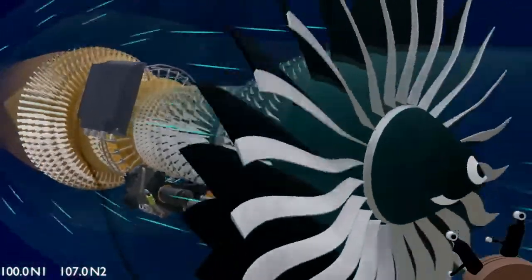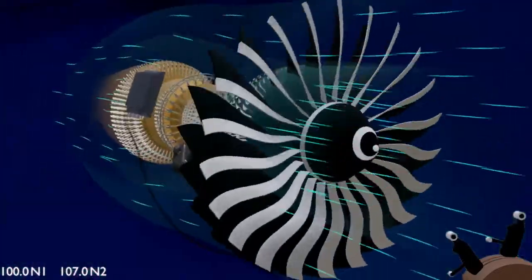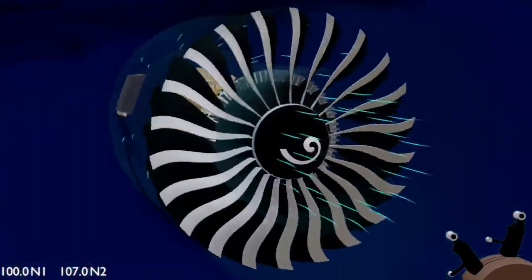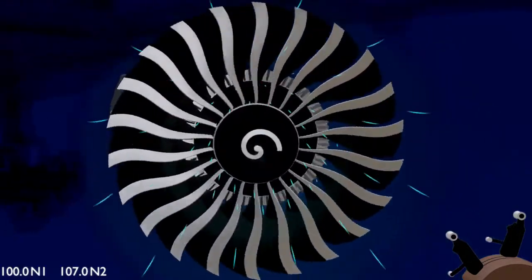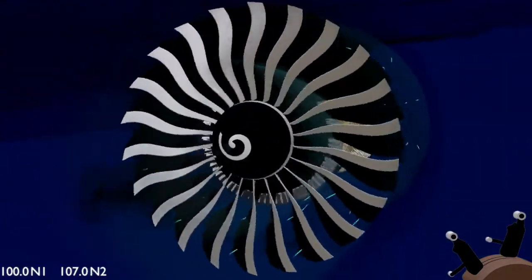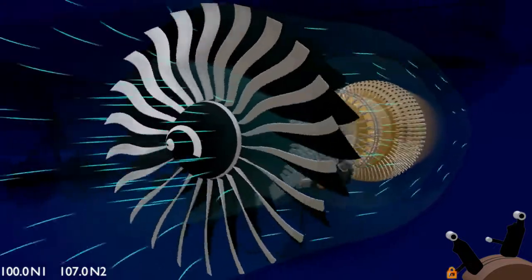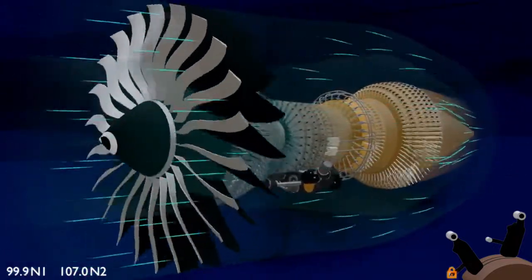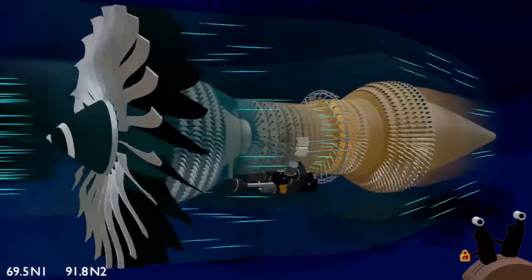Now let's operate the engine thrust reverser. The forward and the reverse thrust lever have an interlock mechanism that prevents simultaneous operation. When one lever is in use, the other gets locked. Therefore, to use the reverse thrust lever, the forward thrust lever has to be moved to idle.